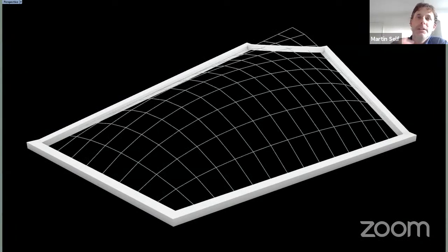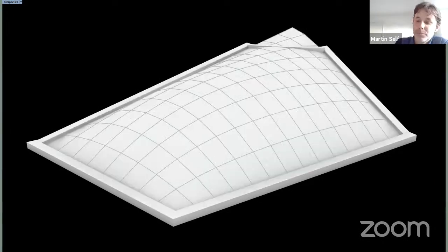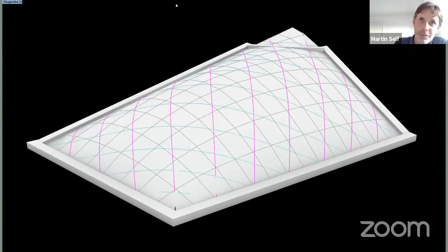So there's a first step of doing an inverted hanging chain type form finding, a mesh form found into an optimized compression shape, and then mapping a continuous surface on that. And then I guess this was a key move. So the lath pieces are following geodesic lines across that surface. So these are the shortest path lines from edge to edge, which have this geometric property that you can follow them with a ribbon of material.